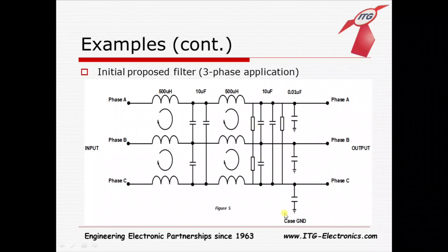These are safety discharge resistors. So these just help the capacitors discharge any additional power they have after a filter is being shut off, so that they're safe to handle very quickly after. These don't actually do any filtering, but they are useful to put in place to allow the filter to be handled more safely. But the next filtering component is obviously another stage of these X capacitors right here, 10 microfarads each. So you can see this is a 2-stage filter, 1 stage here, 1 stage here.